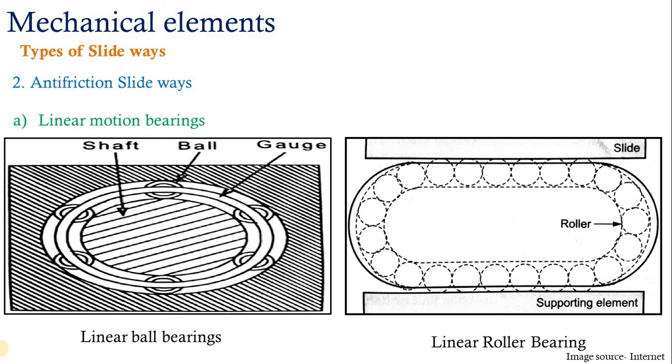The unit consists of bearing, block and rail. The unit is constructed in such a manner that each of the rows of balls rolling over the rails comes into contact with the raceway at an angle of 45 degrees. The race is in line contact rather than the conventional point contact. The system is capable of withstanding equal load in any direction.